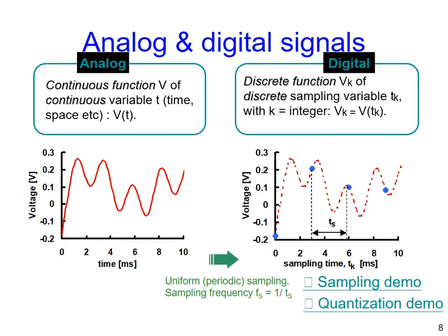For the highest frequency to fully represent it, just like this. So what is the fundamental idea? For each period, you need 2 samples. Got it? Okay, that's it. You don't need to take any class related to Fourier transform or linear system. That is the best I can do. Keep this in mind: for the highest frequency, each period, you need 2 samples in theory for the best representation.